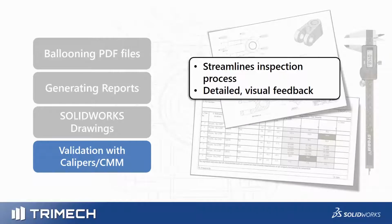So whether it be digital calipers, or something like a CMM or a FARO arm, or something simple like manual data entry of those dimensions, you get really nice visual feedback of whether or not your parts are inside your tolerance range or outside of your tolerance range, with green indicating good parts and red indicating bad parts.